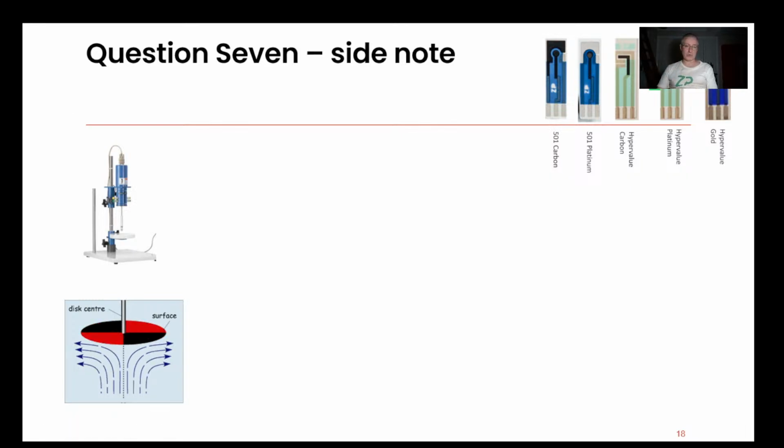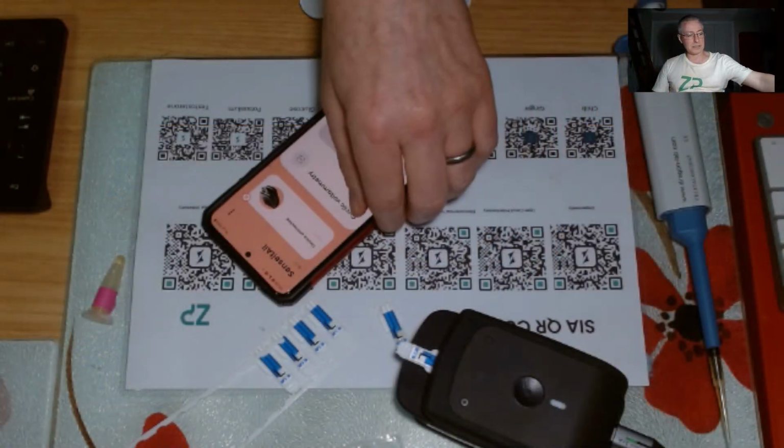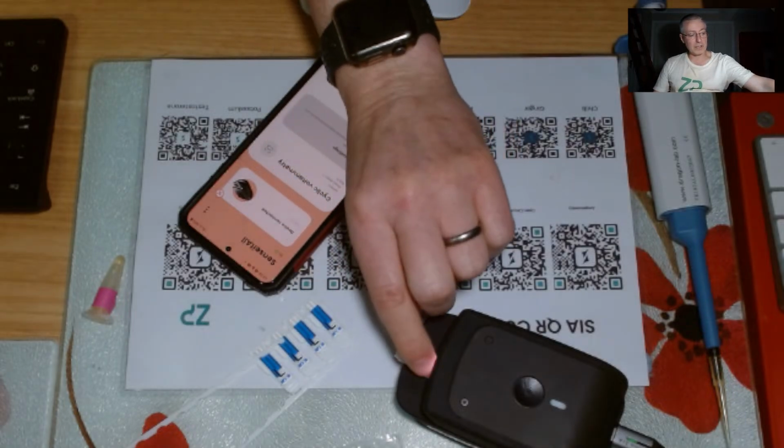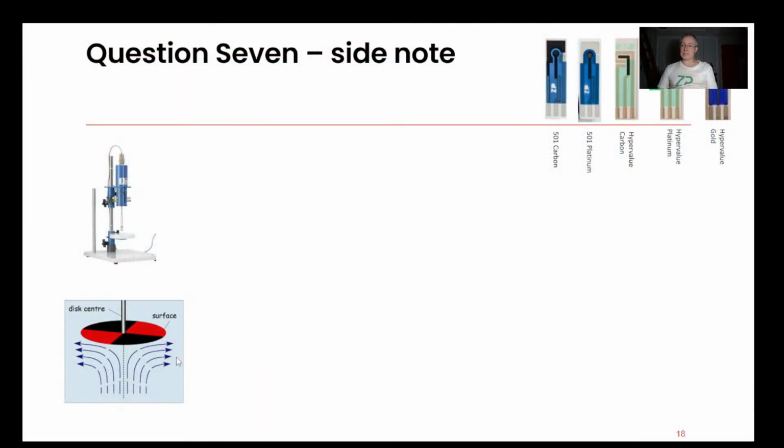Now the reason I think they hold you back is, I'm just going to make a side comment here. If you're going to develop electrochemical biosensors, develop them on instruments that look like the product you're probably finally going to release. When you do use hardcore analytical setups like this, it's really taking you away from the point of care diagnostic, or even the wearable. I've got a wearable on my wrist here. It's taking you away from the final product. You could gather loads of data, but translating all that data back onto the product that you're really trying to develop is pretty tough.